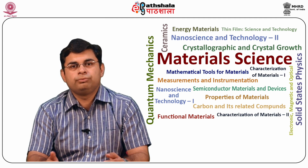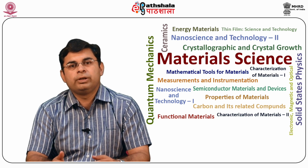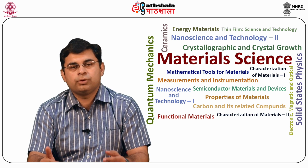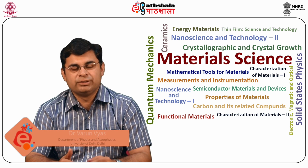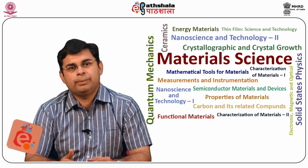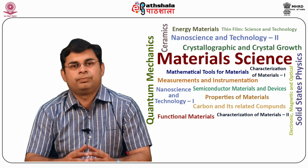In this module, we studied various kinds of bridge circuits. First, we looked into bridge control circuits and various types of bridges that are used for measuring unknown resistances. Under the DC bridges, we studied the Wheatstone bridge, its circuit design and its sensitivity. And in the end, we studied the Kelvin double bridge and how it is used for measuring resistances less than 1 ohm. Thank you.